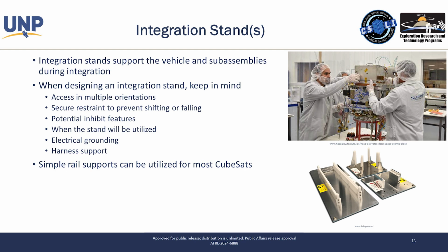You have to keep in mind when you're going to use the stand. Is it going to be used only in the clean room during assembly? Is it something I want to be able to go into a vacuum chamber so I can support my system while it's under test? Is it something that needs to go in a thermal chamber and pass all of the same environmental material standards as the flight system? That's a very key and important piece.